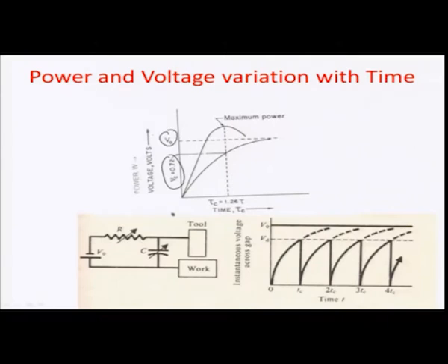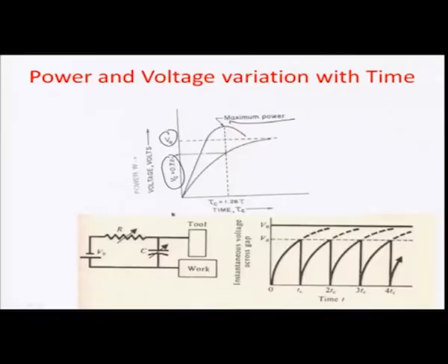Okay, so the operating point of the capacitor, or the capacitor voltage, is only about 72%, and that corresponds to the maximum power. You can see here in this particular figure with respect to the time constant, you are plotting voltage, and you can see that corresponding to this point right here, 72% of the operating voltage, you have the maximum power, and simultaneously calculations were made doing that.